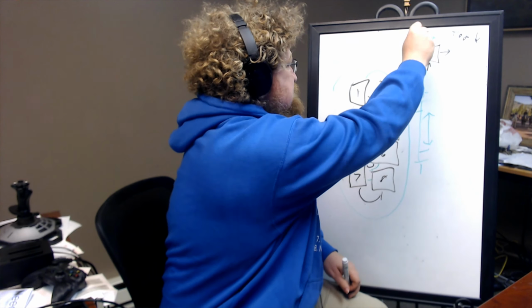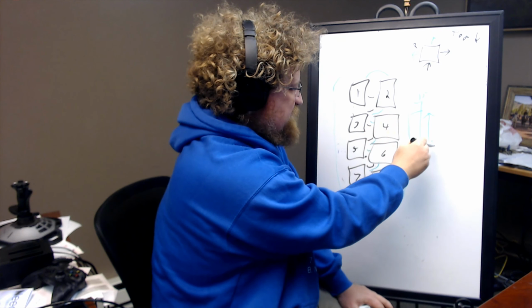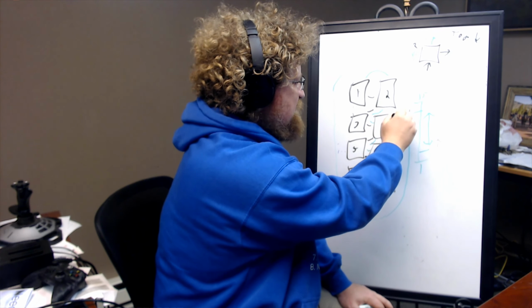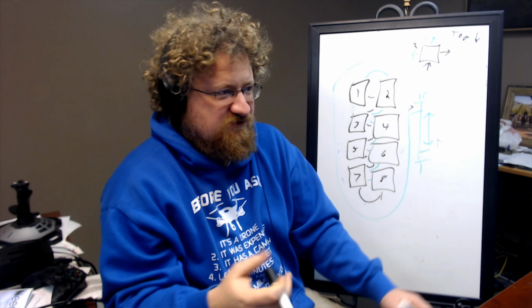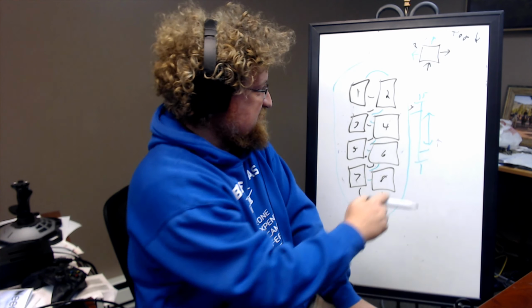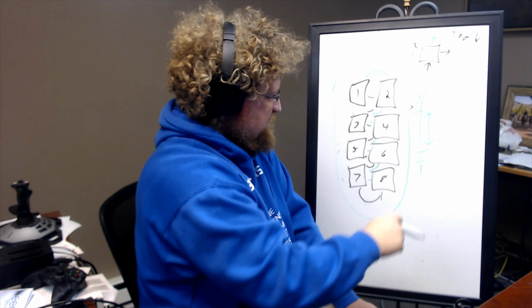So, if both of the signals are on, so like when it's above this side and above this side, the charge can automatically be shut off, and it reads back as that battery's being charged to whatever amount it's set to, which can be set basically in the hardware at various different points.